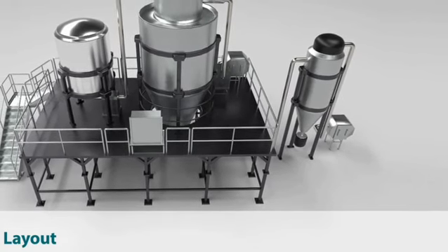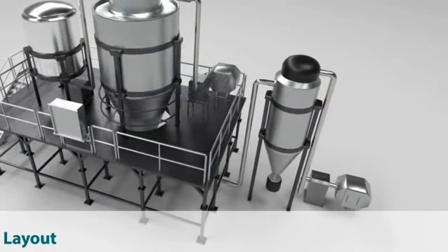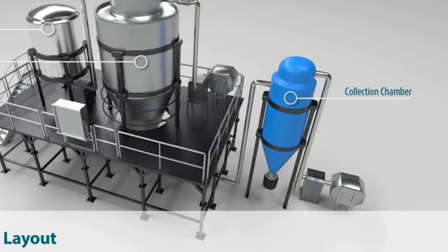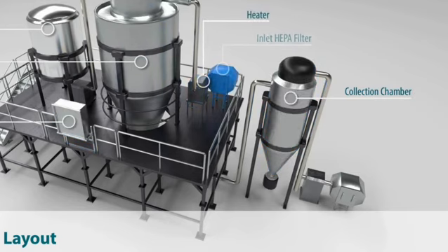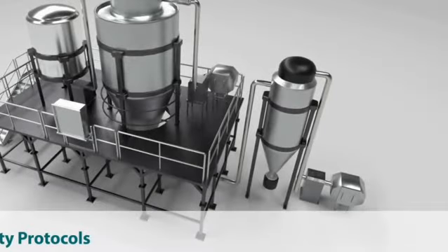Now let's talk about the advantages of spray drying. First, it is very fast, capable of processing large volumes of liquid quickly. The powders produced are stable and have low moisture content, which increases shelf life and reduces microbial growth. Spray-dried powders are highly soluble, dissolve quickly in water, juice, or other liquids, and retain the flavor, color, and aroma of the original product. Atomization allows for uniform particle size, which is important for mixing and consistent quality.